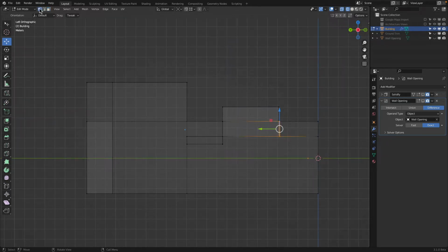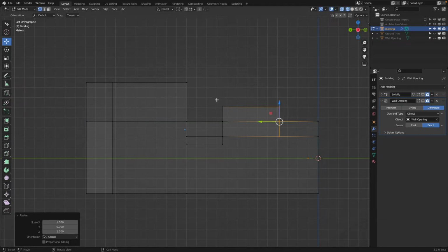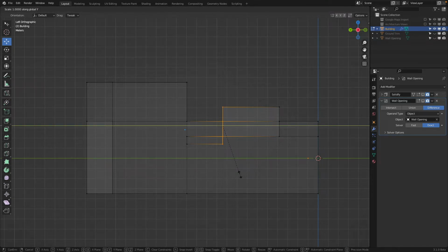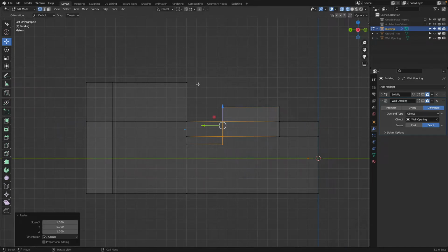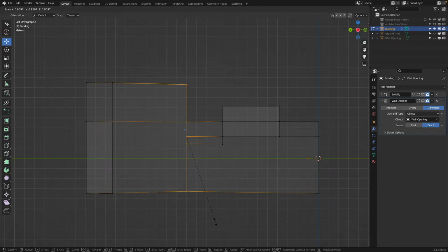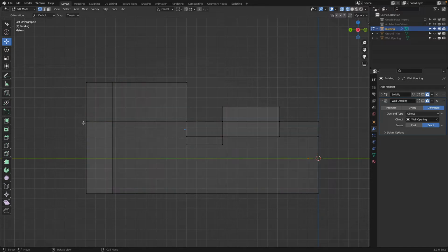That's easy. Point select, AA, B, select all this, and then S and Y and 0, and enter. AA, B, select this, S, Y, 0. So what does this actually mean when I say AA? Select nothing. B, now draw a selection. S for scale, but along the y-axis to 0, that straightens them out.